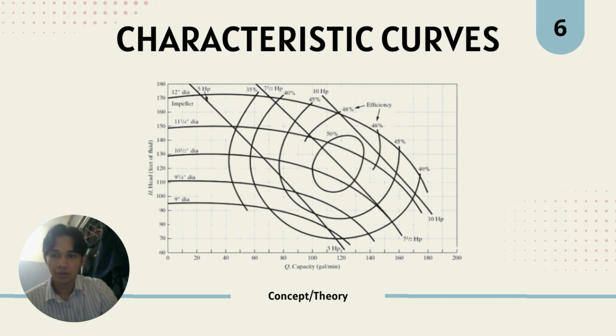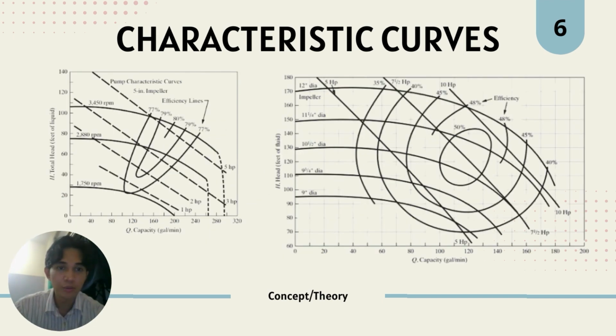As shown, when a characteristic curve for just one rotation rate or impeller diameter is available, the approximate characteristic curve is desired for another rotation rate or impeller diameter. The affinity laws for a centrifugal pump can be applied. As you can see in the following characteristic curves, for a given centrifugal pump, the characteristic curve moves upwards with increasing rate of rotation, and moves upwards with increasing impeller diameter.